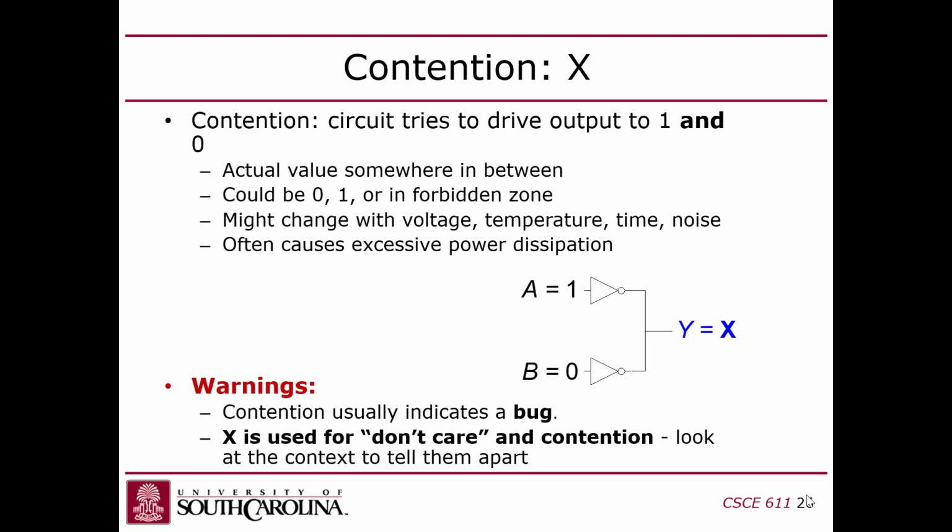If you specify X in your code, that means it's a don't care, right? So you can assign something as X, in which case you're telling the synthesizer you want it to use that to minimize the circuit, to optimize the circuit. You can also, in some cases, use that as an input too, in case statements, which I'll cover in a minute. But generally you can type in X, and it means don't care.